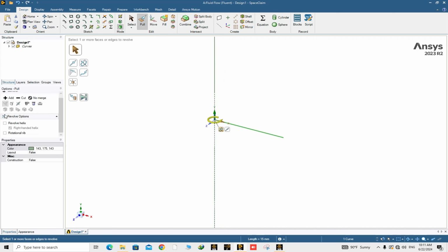And here from this box, actually options, activate Helix. And here the height of the twisted tape should be 2200, but I said that I want to make it bigger than the real one, so I put 2500, and the pitch would be 110.